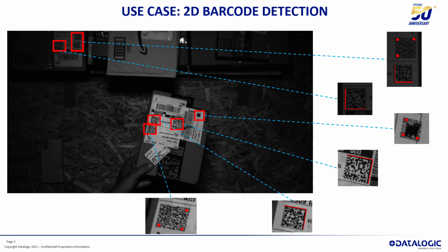The goal is to decode barcodes, but the block that takes a lot of time is the localization of the two-dimensional barcodes. So the idea here is to detect the finder patterns of the barcode. Here, for instance, you can see in red the L of the Data Matrix finder pattern, or the three red spots of the QR finder patterns. And the binary neural network can effectively speed up this kind of application.